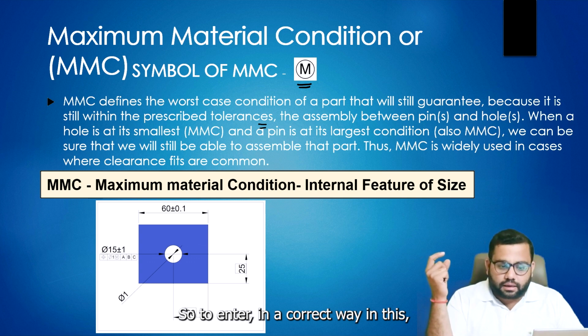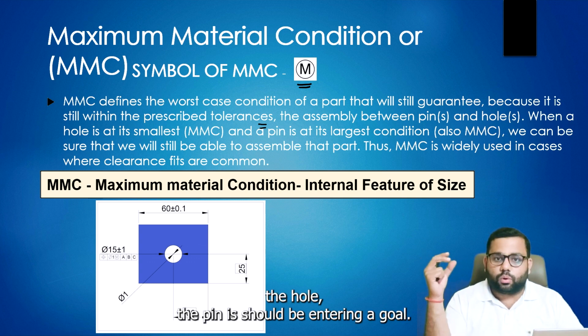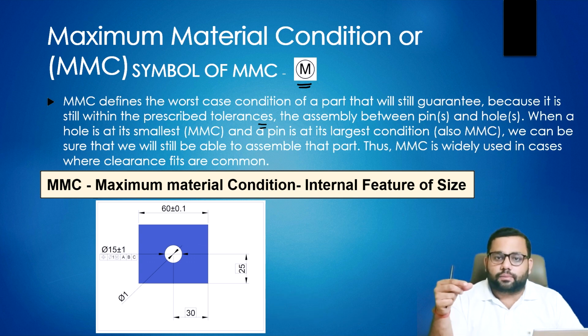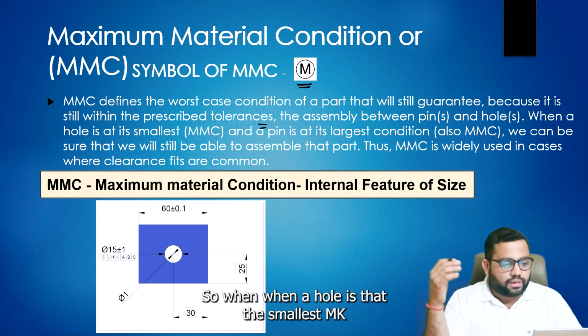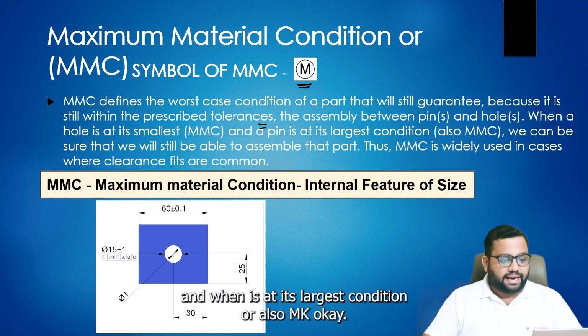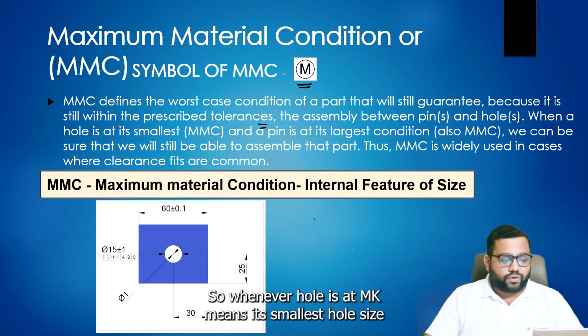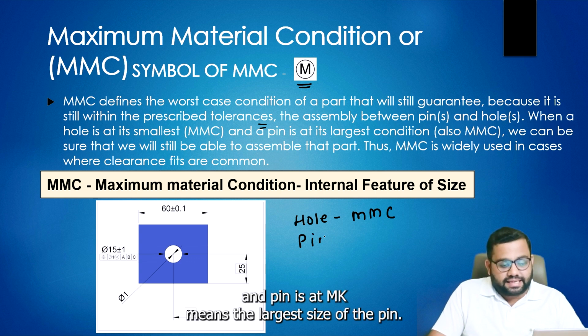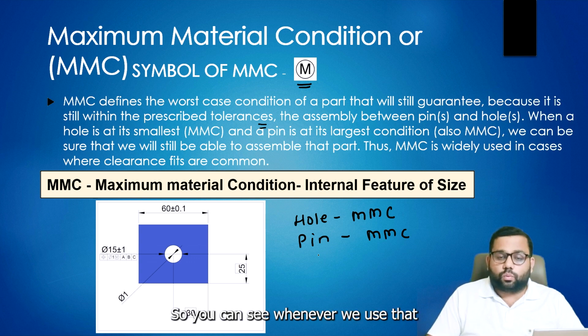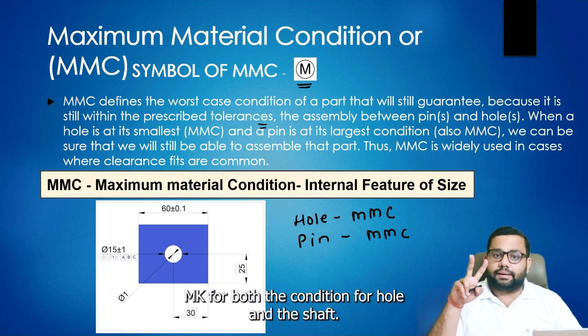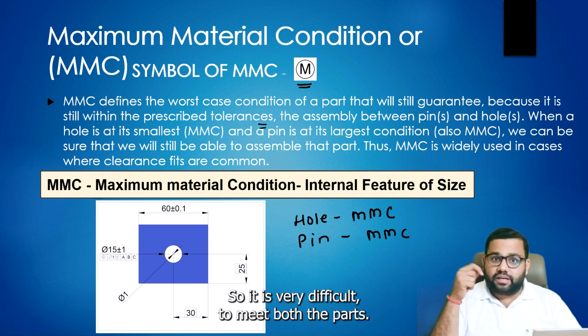To enter correctly, the pin should enter the hole. When the hole is at MMC, the smallest hole size, and the pin is at MMC, the largest pin size, it is the most difficult case to mate both parts.